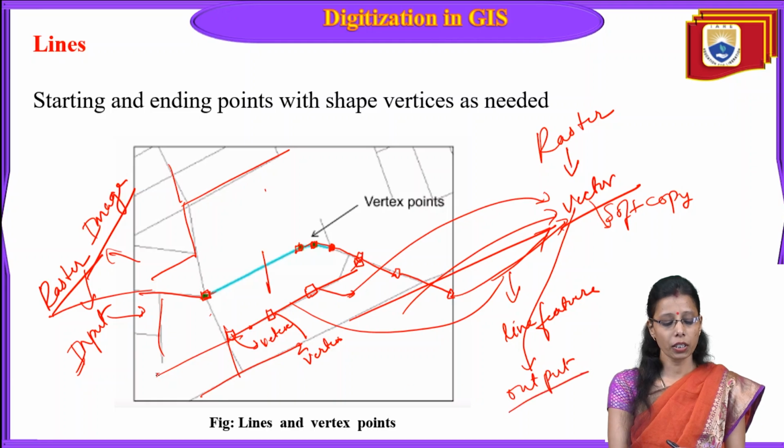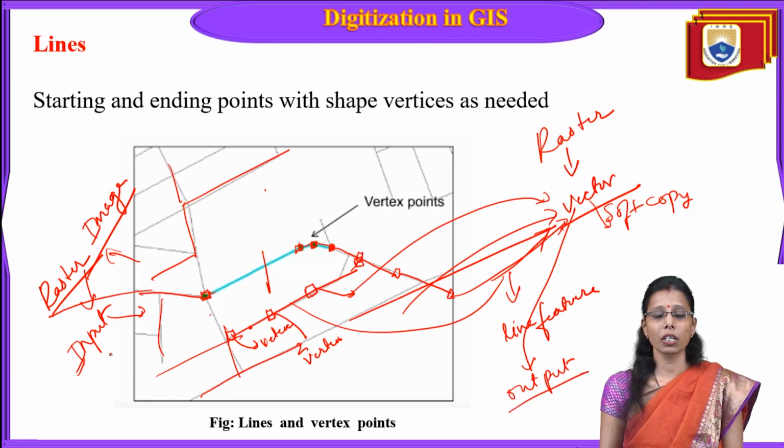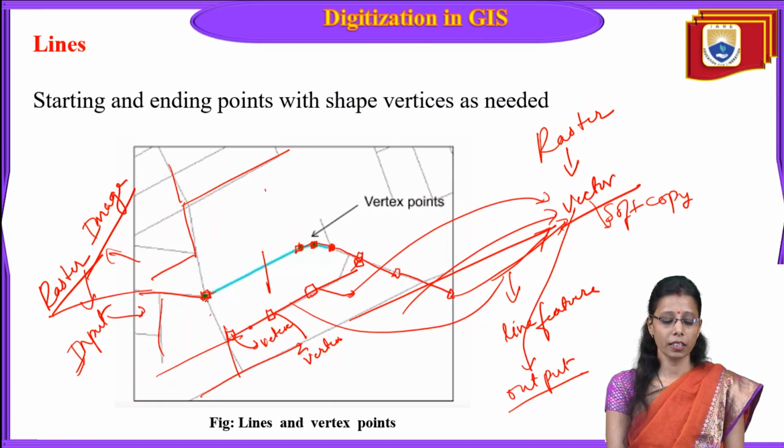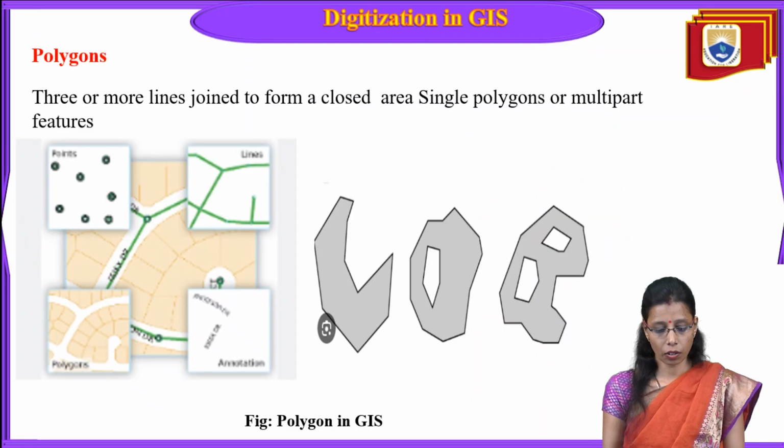So we just input the raster image and we convert the information to the vector by just digitizing. Digitizing means we have to start drawing the line over the image. That can be possible in the software. It has a tool like pen or editing tool. With the editing tool, we can just snap this one by one, and later we can finish and we can add the non-spatial information also. This is how it looks like.